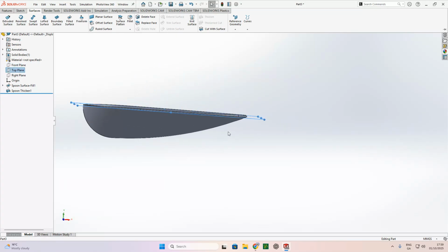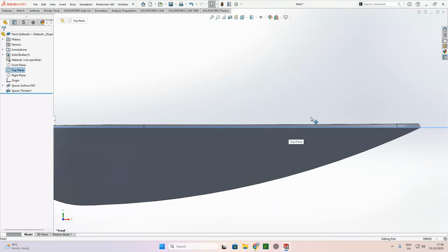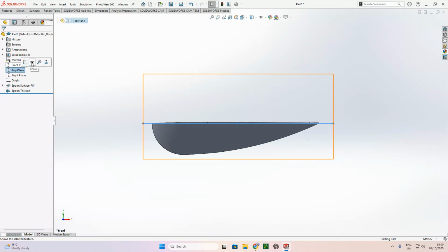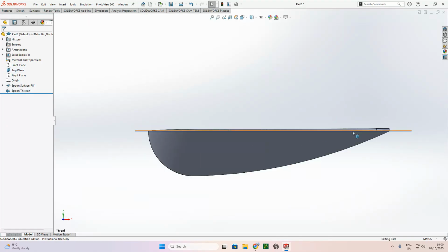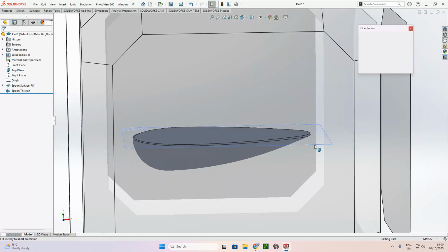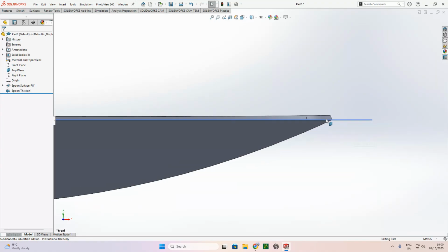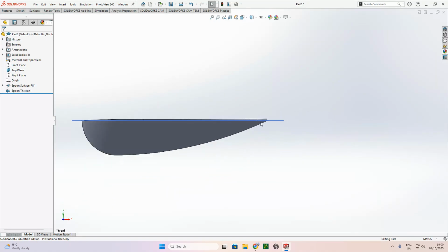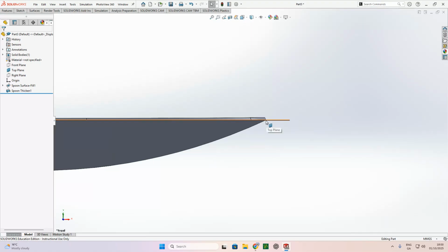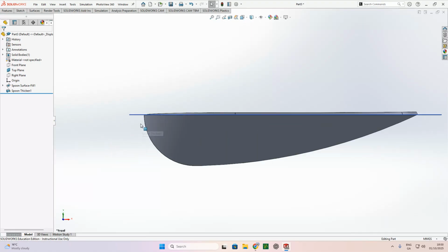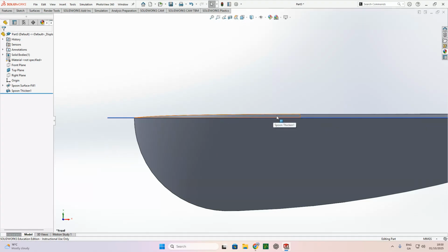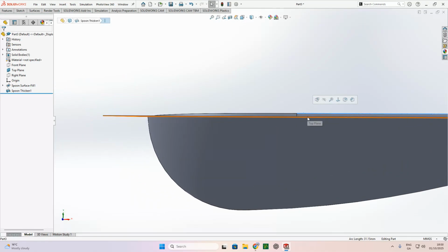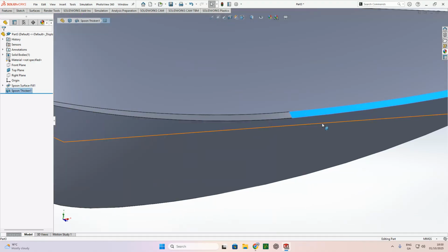If you see, the top plane is actually, you see that blue line there. If I select it, I turn it on, I'll click show. Notice how the top plane is actually going through the object, but it's cutting through it at the exact lip point that I want. So that was important when I actually started my modeling. I want everything above the top plane to be gone. Okay, so there's a little bit of material above the top plane, as you can see there. It's all sitting above the surface. I want all that material essentially to be gone.